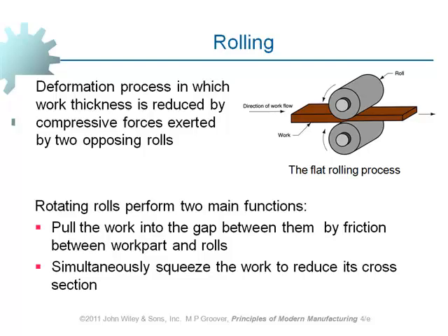However, if the same process is performed at a temperature which is well above recrystallization temperature, then what happens? As I said before, new grains are formed. In the new grains, there are also new dislocations present. So you can still continue the deformation and keep going for some time.